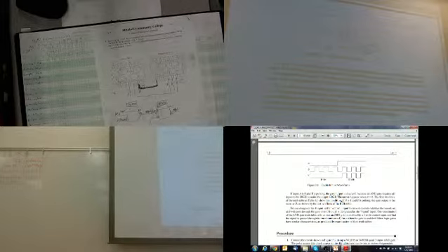And if I turn this scale knob, notice that this goes to 10 volts per division. But it's only half of the square, so that still means it's 5 volts. So it tells you the same answer. You can still read the amplitude off of the oscilloscope by looking at the volts per division. So I'm going to put that on 5. And now you have everything set up.